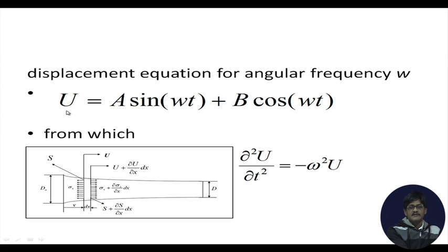We say that the displacement is going to be simple harmonic, and it's going to be addition of these two terms to represent a general simple harmonic motion. These are displaced, with a phase difference from each other by 90 degrees. So we are saying the displacement is simple harmonic. You might say, why? I will say because it's vibrating. All cyclic motions are ultimately simple harmonic motions, and therefore we represent the displacement by this particular general expression. That's good, but what comes out of it?